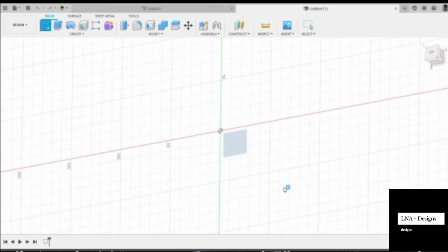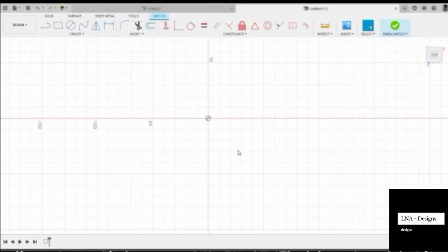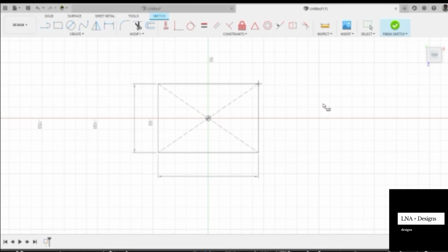So I'm going to create a new sketch. Click sketch. It's a bottom plane. We are going to select the bottom plane, and we are going to start from a basic shape, which is rectangle. I'm going to show how to use the different types of rectangles in a sketch. It is center, 3 point and 2 point.